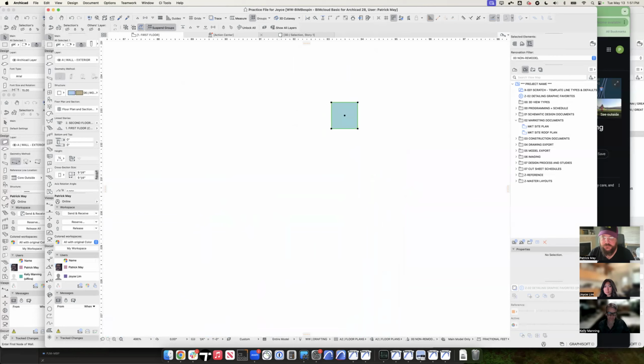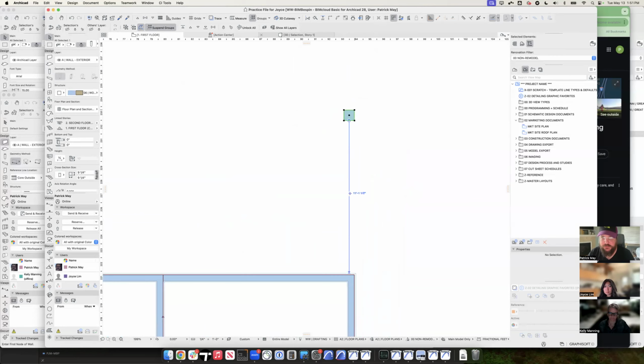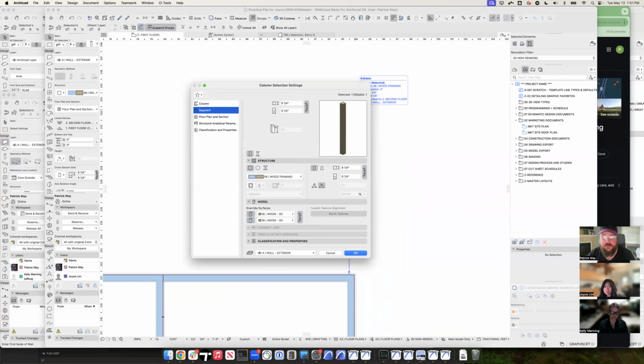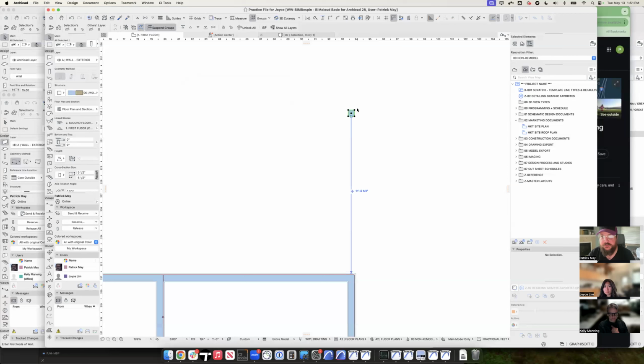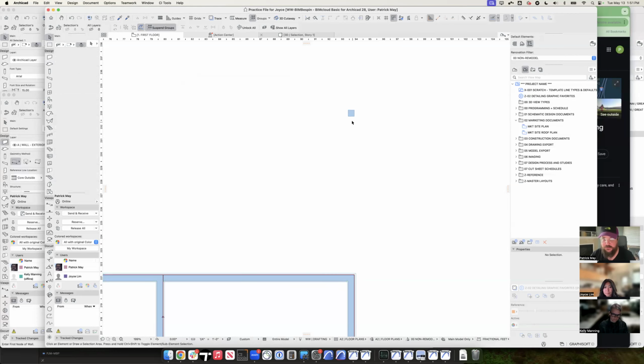Yeah, so there's that column. Now I put the reference line on the upper right of that. So as an example, if we said that this is going to be a 5.5-inch column, I reduce that down. Notice that that fixed point right there stays where it was. And this is one of the disadvantages to the column: there's nothing in that column that says the reference point is here just by selecting it, unlike the wall where I can actually see that that reference line sits right there.